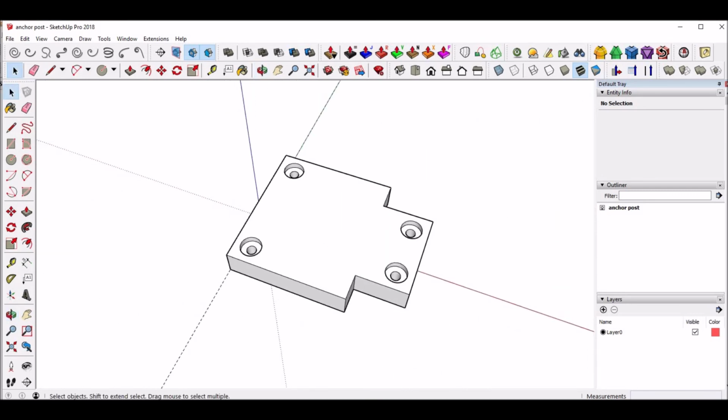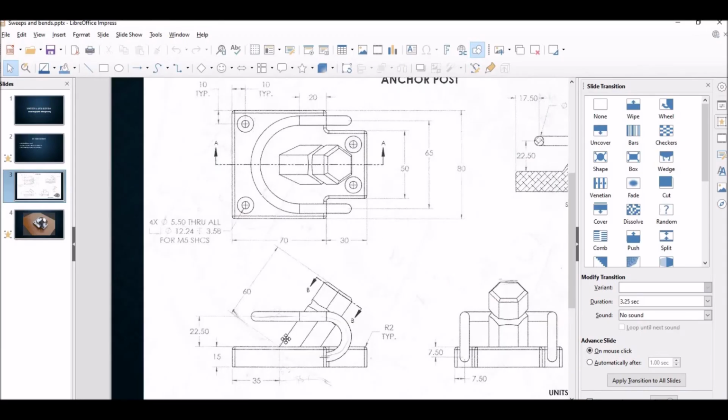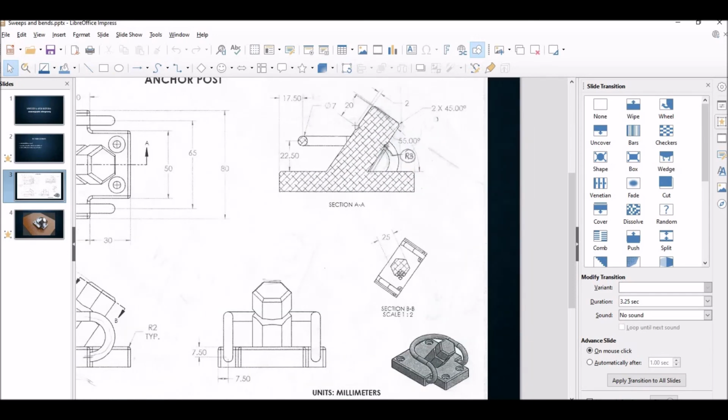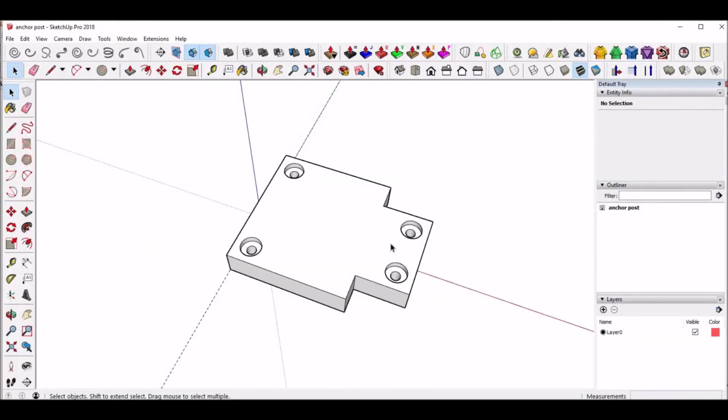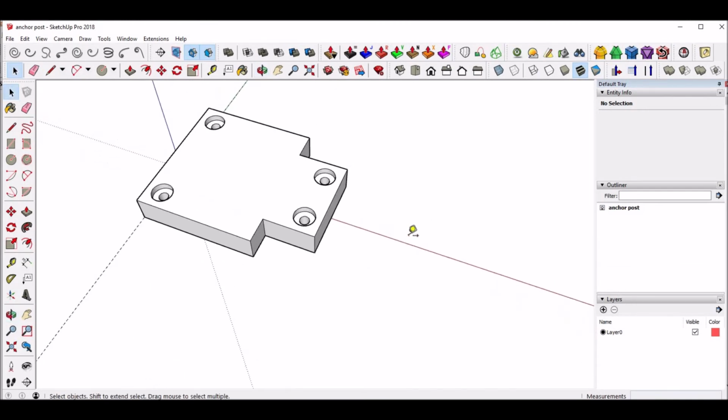So before I finish this section, let's at least build the hex head. We know it's 60 millimeters in height, 25 in diameter, so 12.5 radius from flat to flat, not vertex to vertex. And that should do it for this video. Okay, so let's make that. So we need our guide here because we got rid of it. Polygon tool, where are you? Right here. 6-sided polygon, it's already set.